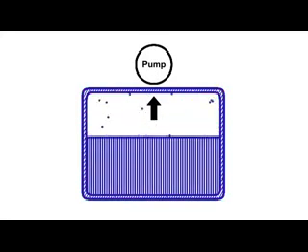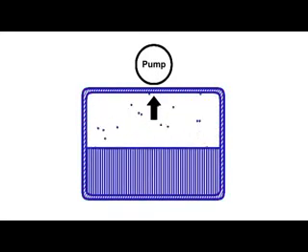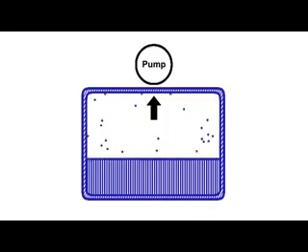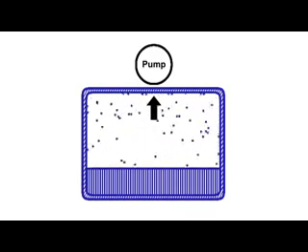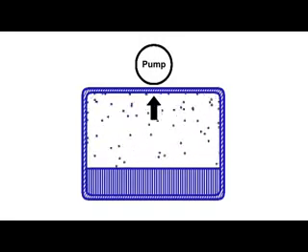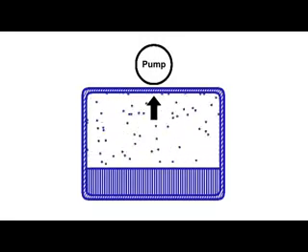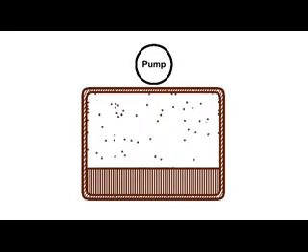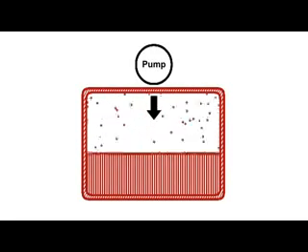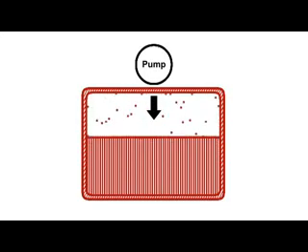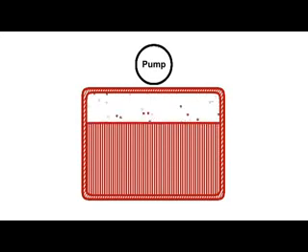The second rule of physics we need to buy into before proceeding is as follows. The boiling point of a fluid is a function of pressure. You already knew it was a function of temperature, but it's also a function of pressure. Low pressure induces boiling. You may think of low pressure as kind of pulling apart the denser liquid molecules and thus changing their state to a gas. High pressure induces condensation. Again, we can think of high pressure compressing the dispersed gas molecules into a denser liquid. And all this boiling and condensing can be accomplished by pressurizing and depressurizing the coolant.